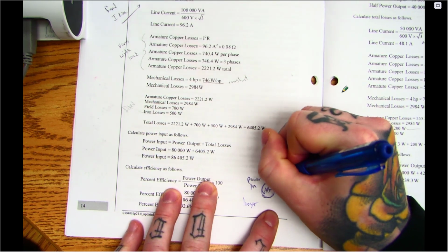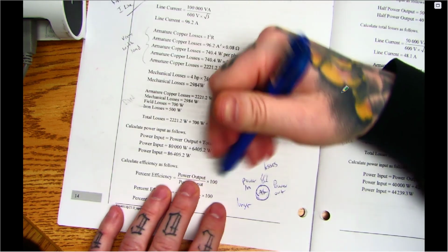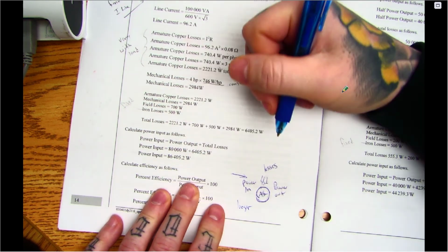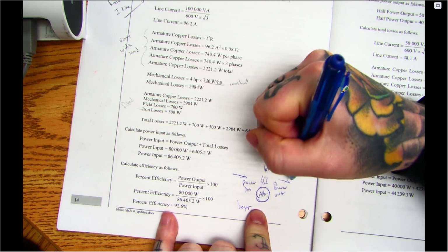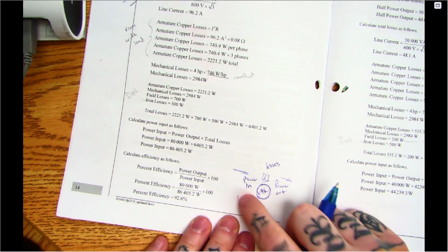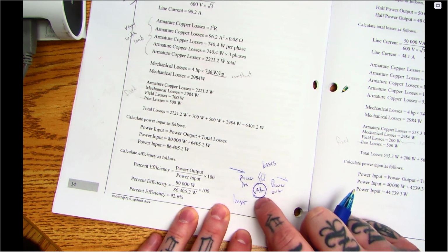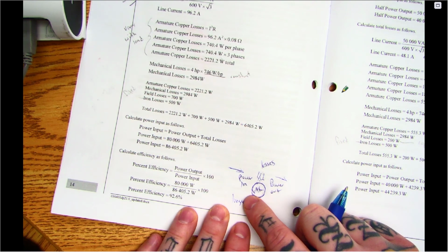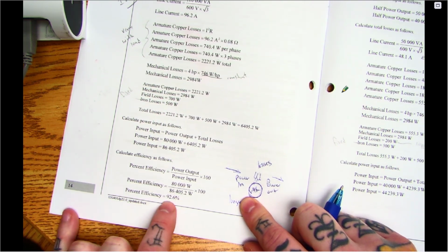So again, due to heat, friction, all that thing. So I have power coming in to the alternator. I have losses, then I have my power out, and this would be to my load. Okay, but I'm always going to have larger in than out because the losses are going to be taken out from my in. Okay, so when I use this calculation, find the efficiency, I can see that it's 92.6%.